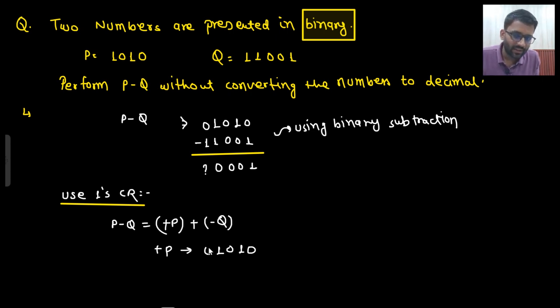Since there is a plus sign, you put 0. These are the magnitude bits shown by the binary. Since there is a plus sign, I can put one more 0. Now it is plus p. It is in sign magnitude form, which equals 2's complement form as well. Are you getting this point? But I will add another 0 here because I know this will require more bits.